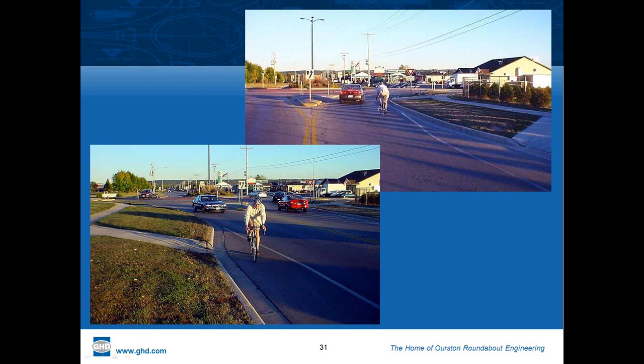If there are bike lanes, they should terminate before a roundabout and force the cyclist to choose whether to become a pedestrian and divert or whether to become a vehicle and take up really the center of the lane so that they aren't passed in the roundabout. The speeds in the roundabout, especially single lane roundabouts, are low enough that cyclists can comfortably move with traffic. The question is, will drivers see them and yield to them? It's important that they stay in the center of the roadway.